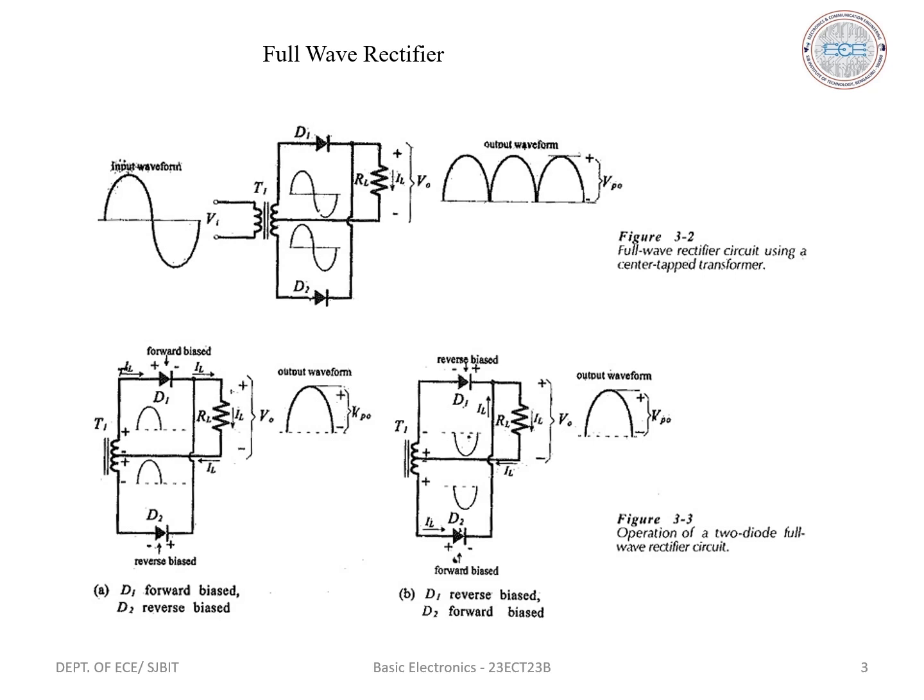Here, diagram A represents the output when you supply the positive half cycle of the input signal, and circuit B represents the output when the negative cycle of the input signal is supplied to the full wave rectifier. The full wave rectifier uses two diodes, a load resistance RL and a center tap transformer as shown in the figure.